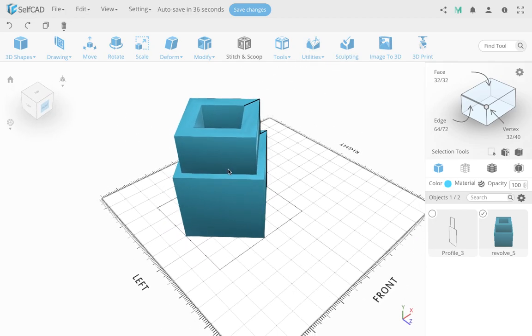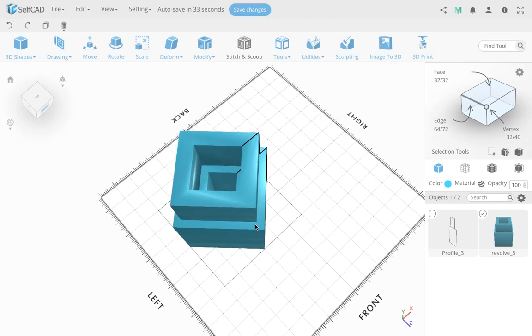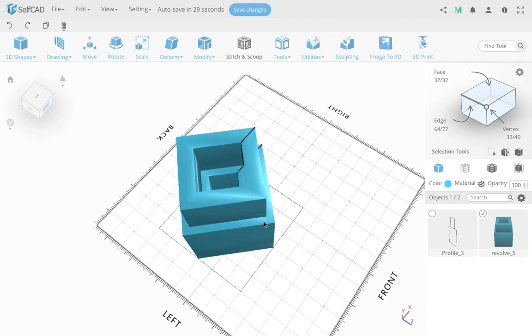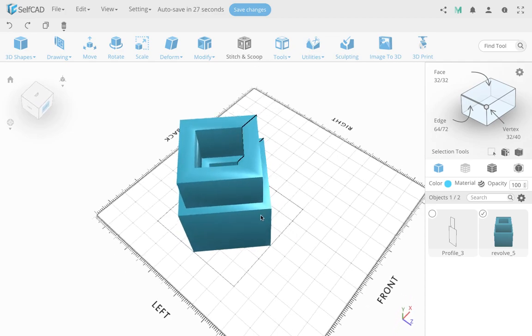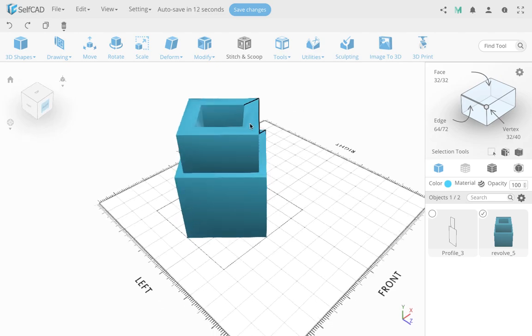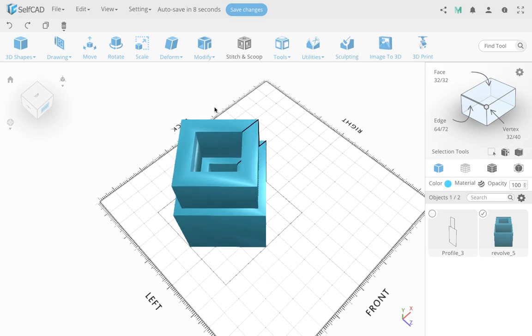You can arrange all types of things, and Revolve is used a lot to create cups, glasses, like wine glasses or those types of things, because it has a hole inside, and you can simply take a spline and draw the outside, and either use Add Thickness to create the inside part, or manually draw the inside part. You make it a polygon, and then you simply revolve around, and you make that shape. For those types of things, it's quite good.